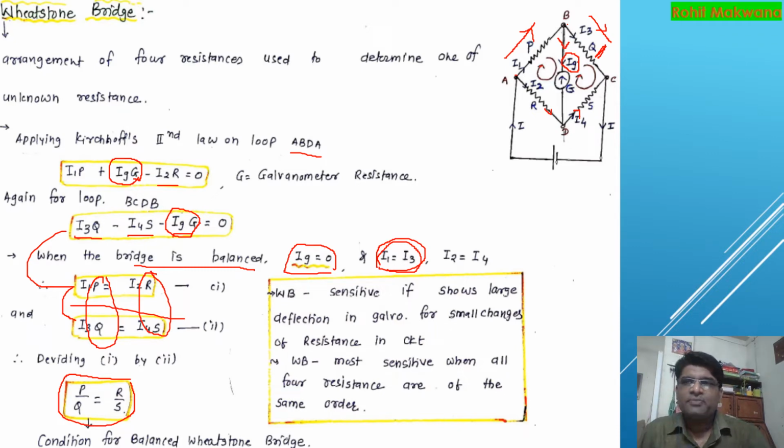Okay. So when you have balanced this Wheatstone Bridge, the potential difference between B and D, where the galvanometer is connected, is 0, because no current is flowing through the galvanometer. And what is the advantage of the Wheatstone Bridge method? Why are we using it? What is the advantage it is offering over a voltmeter or any other devices? Okay, so it is a null method. The internal resistance of the cell or even the resistance of the galvanometer does not affect the null point method, right? So it doesn't affect it.